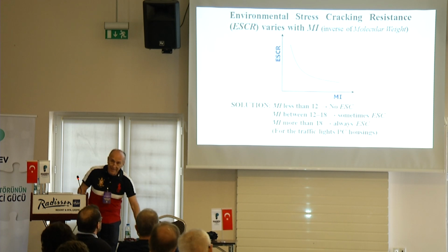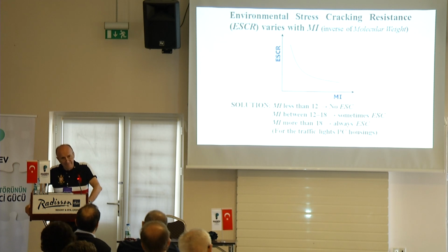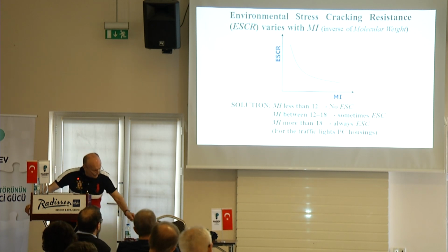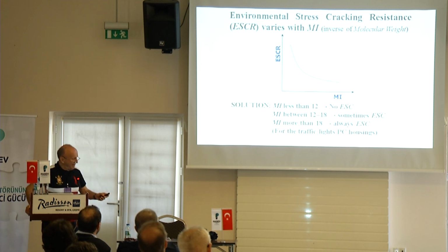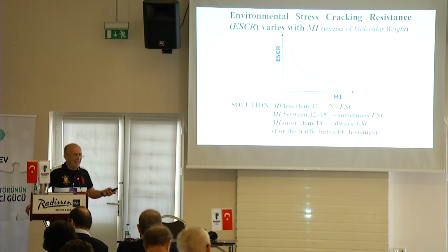In other words, the resistance to cracking drops as the molecular weight becomes smaller. I knew that from a very old book. And then by making measurements and correlating to performance, we said that if the melt index was less than 12, they never had a problem.